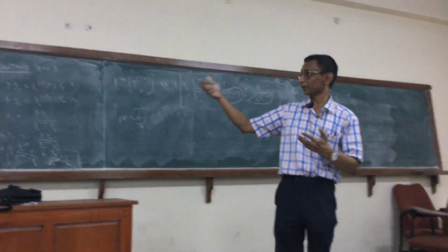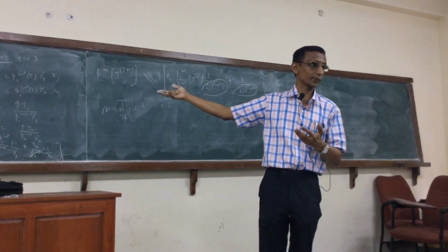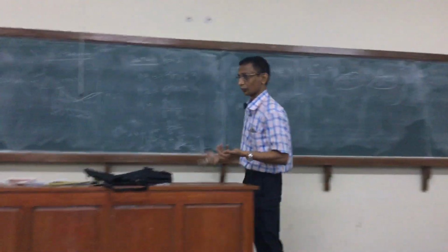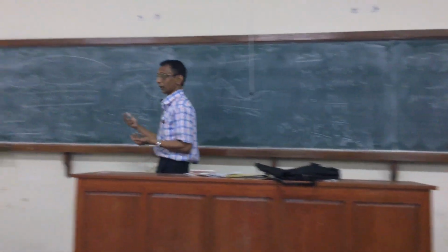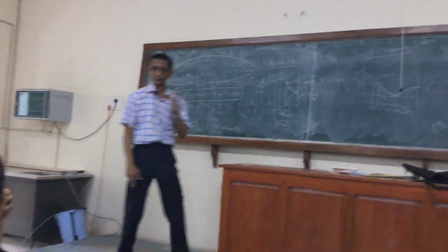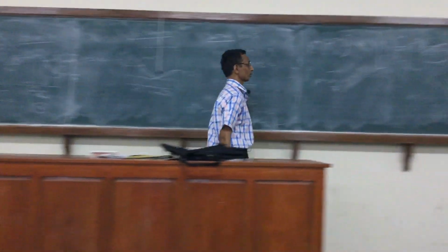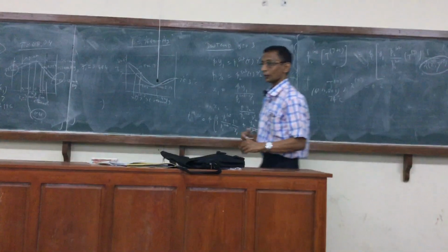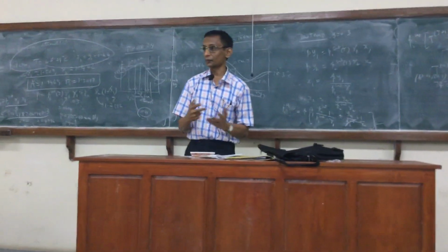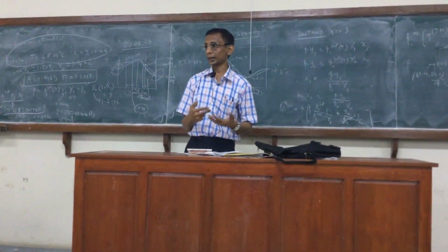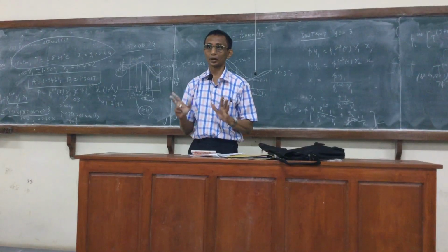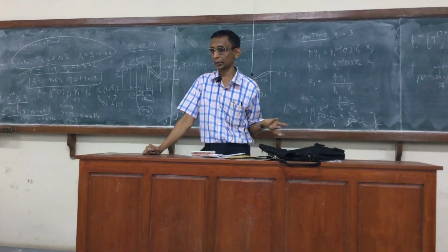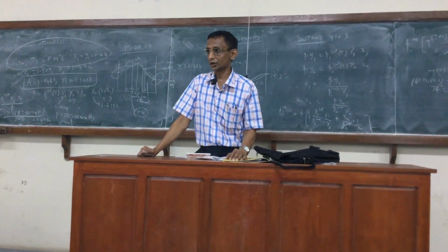then you have to take that also into account. Typically, we assume this temperature range is anyway very narrow, 80 to 68.2. Very narrow, so you can pretty much assume that the constants you are calculating are independent of temperature. So basically, the dependence on x is what is going to dominate in this case. Otherwise, the algorithm is very similar to the ideal case, bubble temperature and dew temperature, very similar approaches. Are there any questions? Now, can you do maybe a couple of algorithm iterations and check if it is convergent?